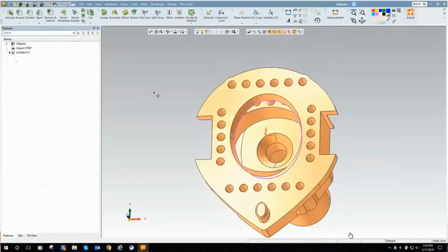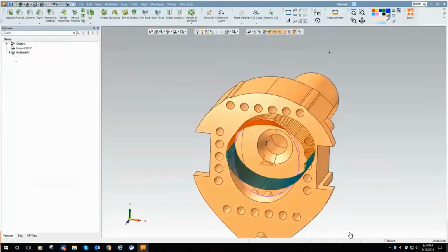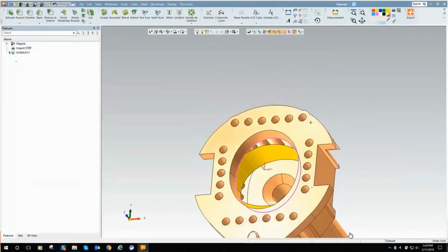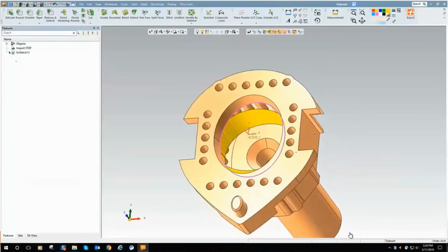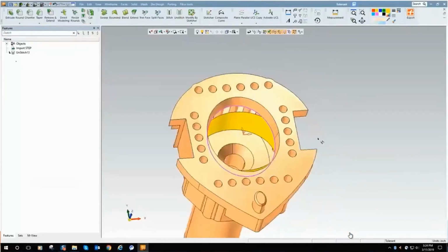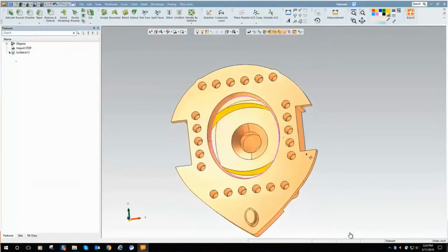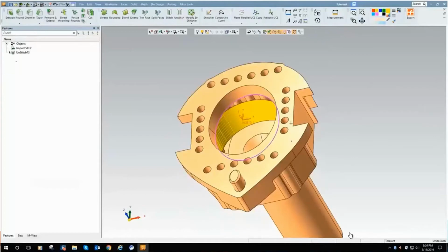So here, the solid tolerance of the part must have been so incredibly loose that it was still joining faces that were either damaged by translation or just really poorly created. And we know this example is way over the top, but it's a useful way for me to illustrate the concept of a tolerant edge and why they may be of interest to you.